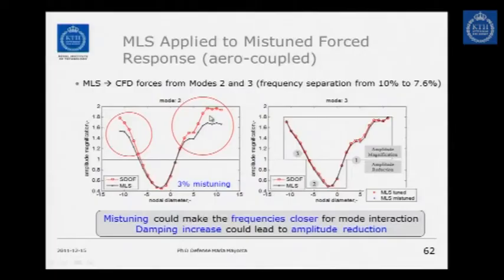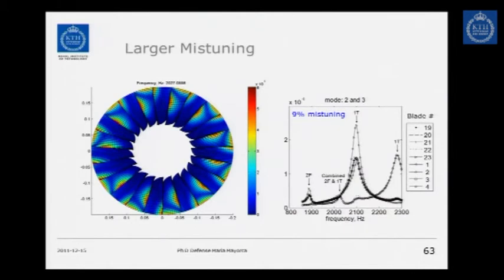So I just show here the difference, for example, of the influence of mode 3 and mode 2 by this small difference when I compare to the single degree of freedom only using mode 2. And then if I dramatically increase the damping and I made the blades actually change the frequencies in the same resonance, I will get a mode shape something like this.